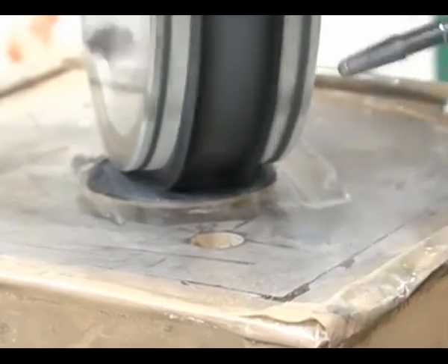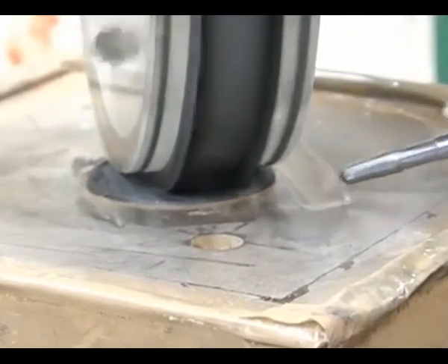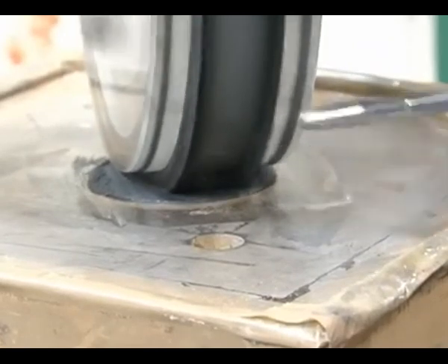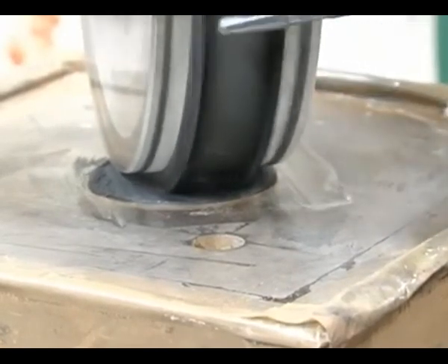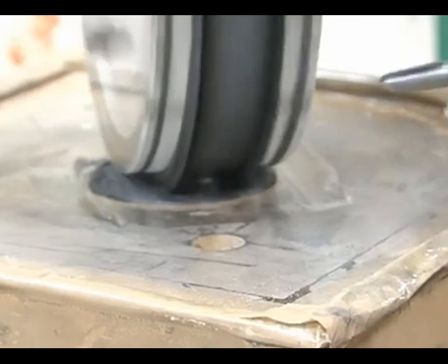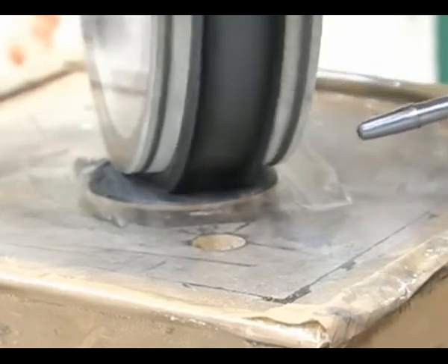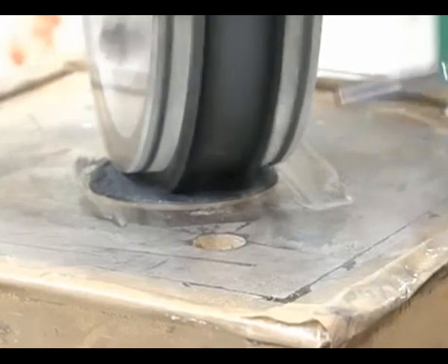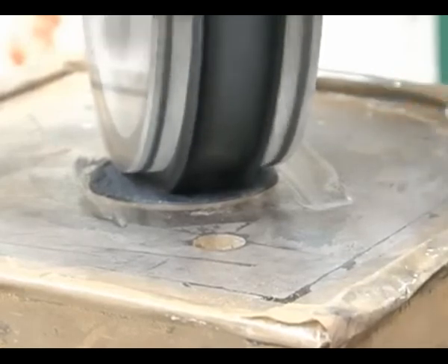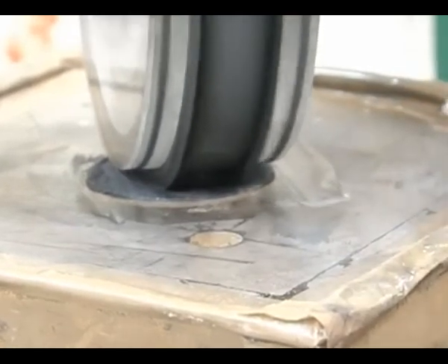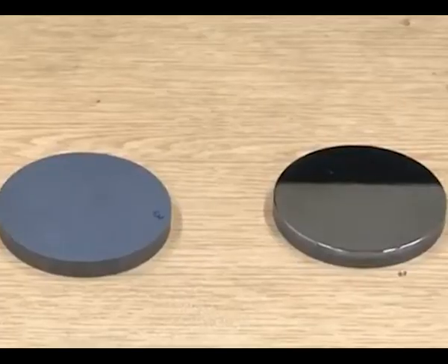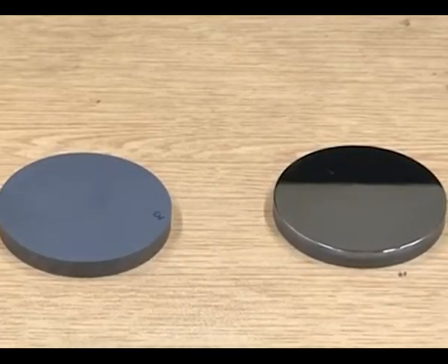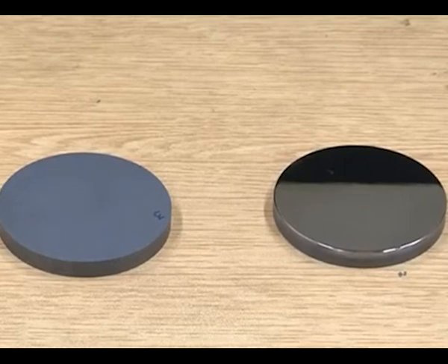It is due to the flow of the MR fluid through the converging gap, because the gap is a little bit smaller than the thickness of the ribbon which is applied on the wheel, and the hydrodynamic action of the MR fluid also creates some normal force. This process is continued till the desired surface finish is achieved. Now I will show you the finished as well as unfinished silicon workpiece surface. You can easily see the difference between unfinished and finished silicon surface.